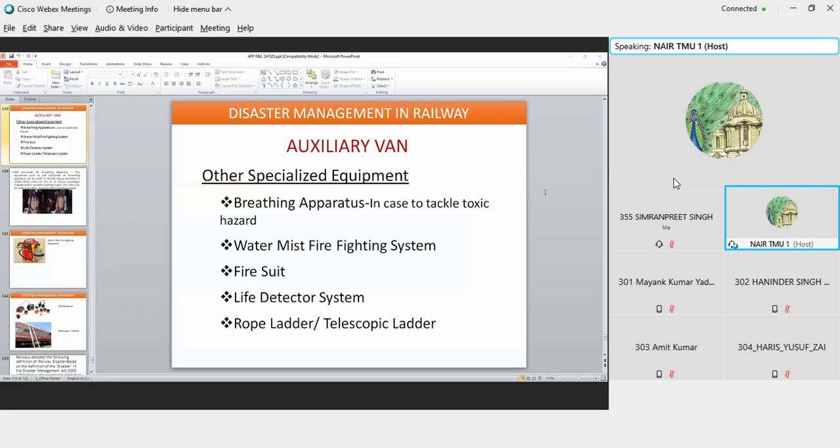But in gradual derailments, you will find it is a combination of factors. The longitudinal forces: I have not provided proper liners on the coach axle box. If the liners have not been provided properly, I have increased the longitudinal clearance, and if I increase the longitudinal clearance, it starts giving me more longitudinal force. Now, this more longitudinal force coupled with a pandrol clip which is not tightened properly will lead to a case where the gauge spreads. So, it is a combination of factors which generally leads to derailments or accidents.